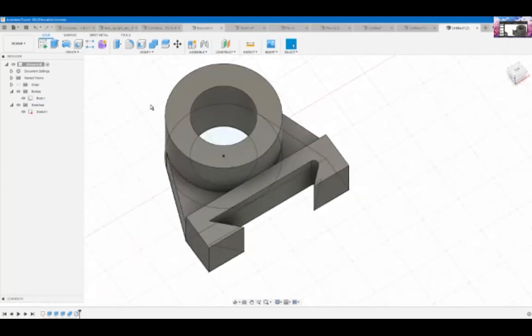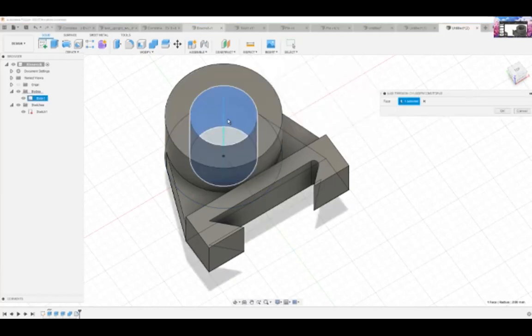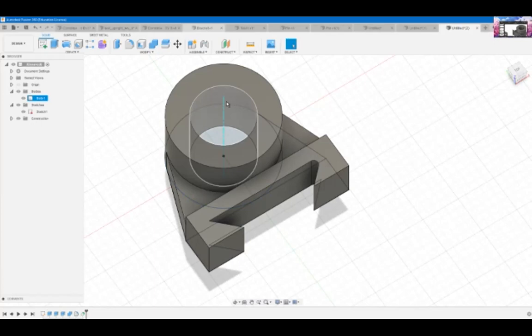For example, if you want to make two axes concentric, you can make the inside faces concentric. However, if this is to change, then that inside face is gone. The mate breaks. You can apply an axis, so an axis through a cylindrical face, and now you have this little guy, which is an absolute representation of the center of this circle. There are far more implications to it than that. For example, you can define, say, a point that is concentric to this axis, but also coincident to this face.